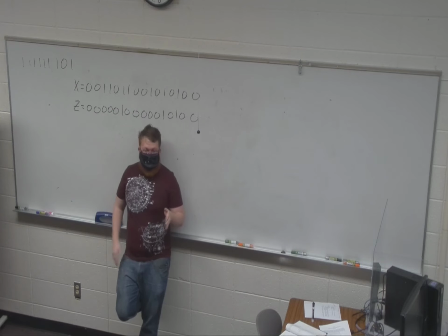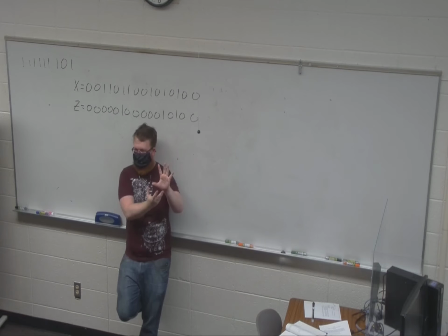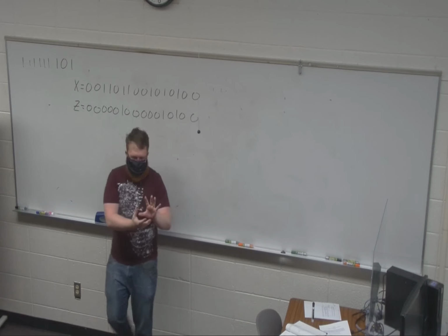And you could delay a whole clock cycle or half a clock cycle, and suddenly if you have a control unit over here telling a memory unit over here what to do, they could get out of sync with each other when that control unit then tries to pull the data back from that memory unit. So we need to worry about timing on this.